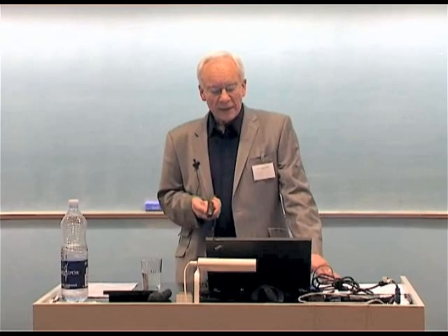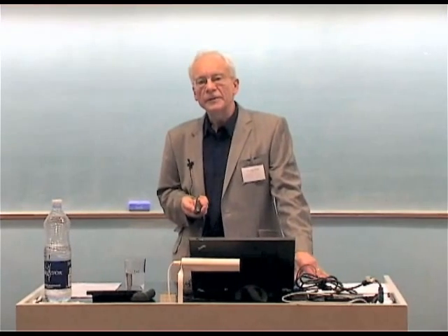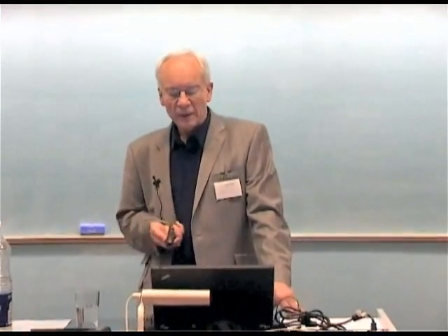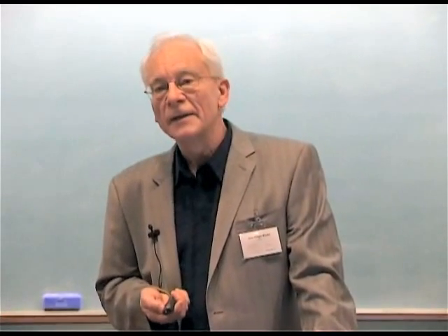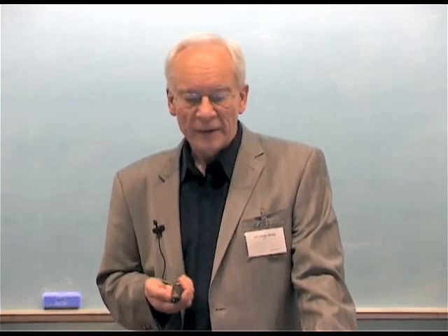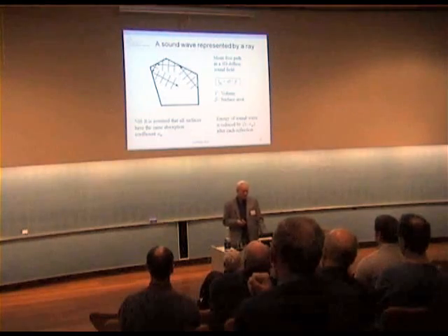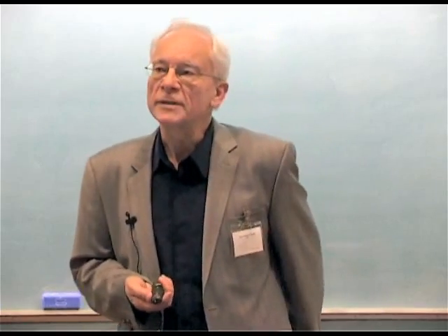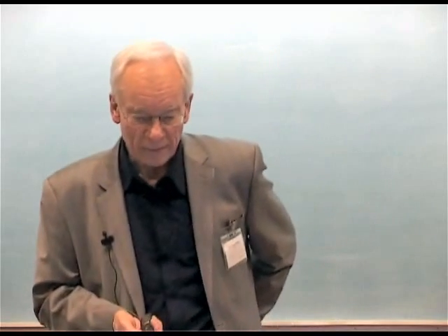It is shown here that we can represent the sound reflection with a ray, following reflections from surface to surface in the room. There will be different distances between the reflections, and it's also a very old knowledge in room acoustics that we can calculate a mean free path, which in a three-dimensional room will be 4 times the volume divided by the surface area.